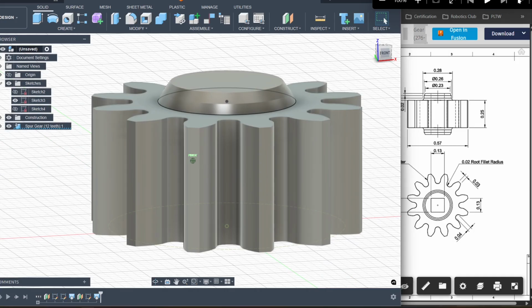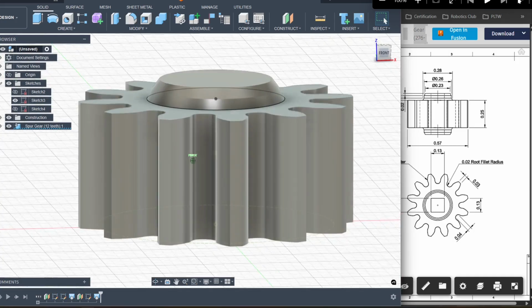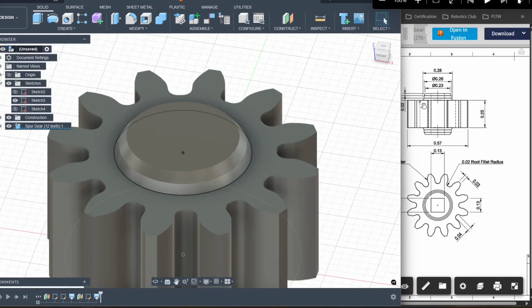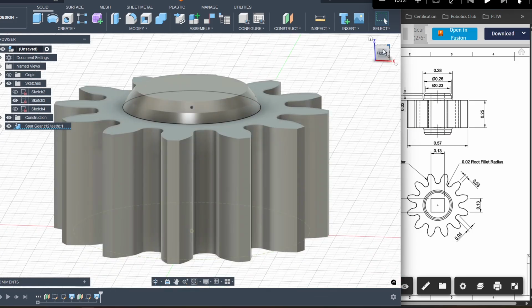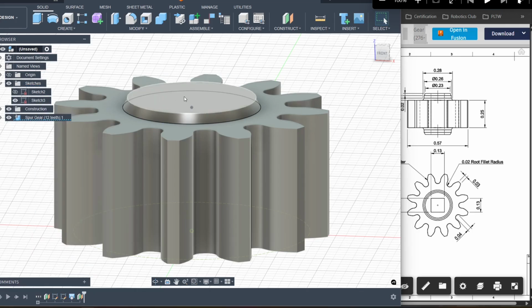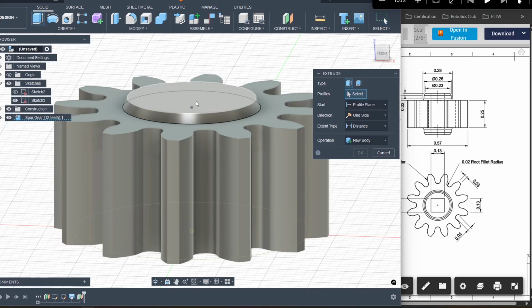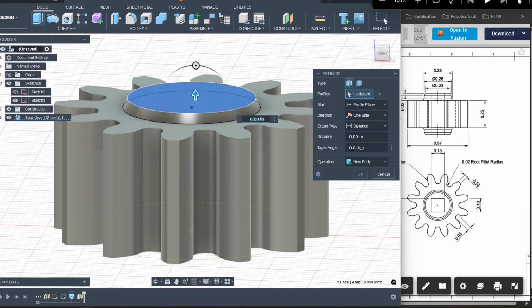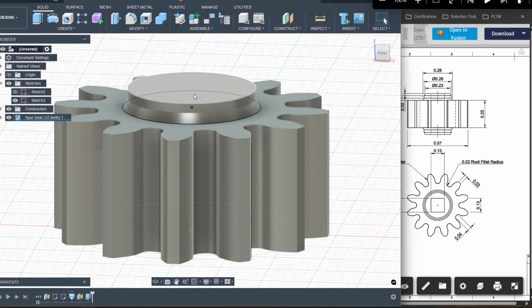And that looks like I've got the thing, so... Oh, nope, I do not, because I have a straight part of 0.2 first, and so I actually should have extruded it before I lofted. And so I can just delete that sketch instead, and then do an extrude here, up 0.02. So I have that straight part first.